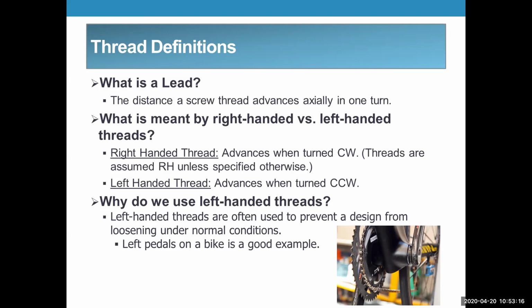And I think that originally there really was not a torque element on those nuts. Now they all have to be torqued like 100 foot-pounds. I think they do vary some, depending on the design, the size of the nut and bolt. But typically, most car lug nuts are 100 foot-pounds. Well, I've seen them upwards of 120 foot-pounds. I think a lot of it has to do with the design of the seat that's on the wheel.